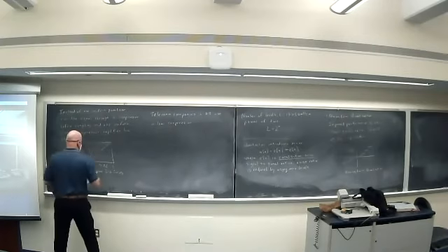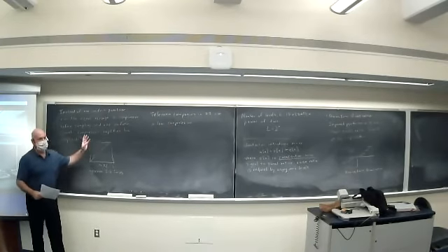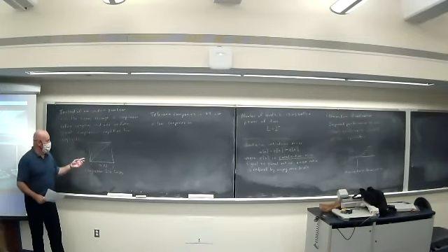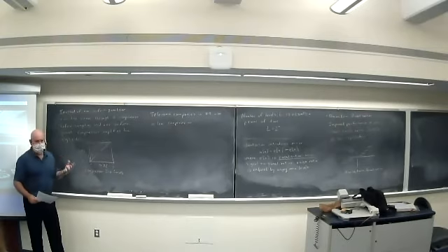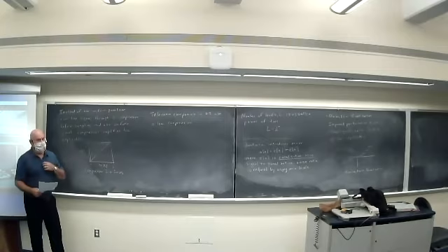What I'm talking about here is running the signal through an analog circuit, a nonlinear amplifier that does this before sampling. So we would run our original analog signal through this compressor to amplify the low volumes, and then run it through a uniform sampler. There is another way that is not talked about in our textbook. You could sample using higher resolution, like 16 bits, and then convert that into 8 bits.